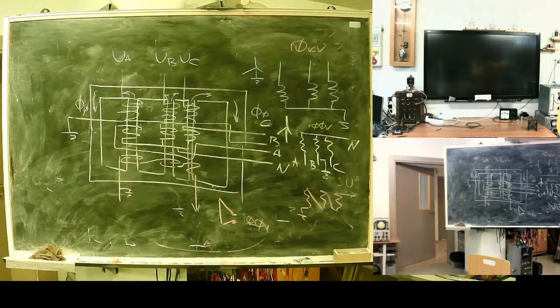It's one common barrel, but inside, each winding has a complete enclosement of steel. It's not the cheapest thing in the world. That's why typically such a transformer will be only on the busbar side. Line voltages are taken with a simpler thing.